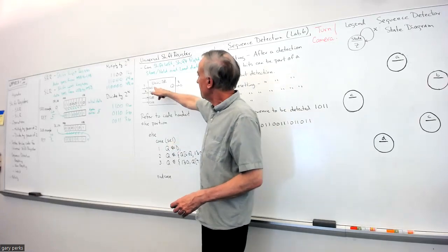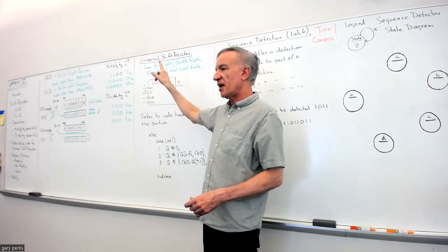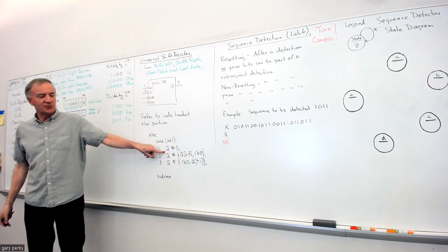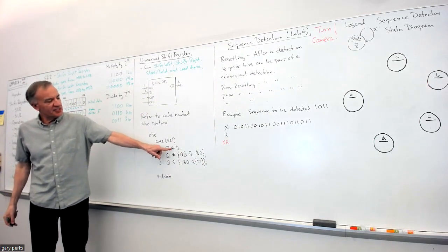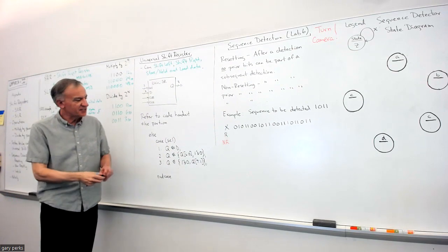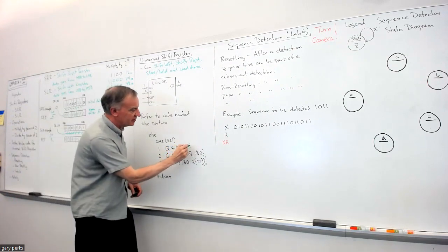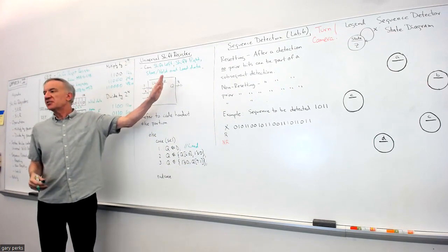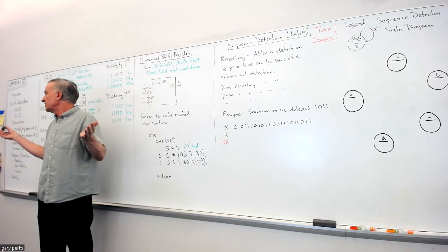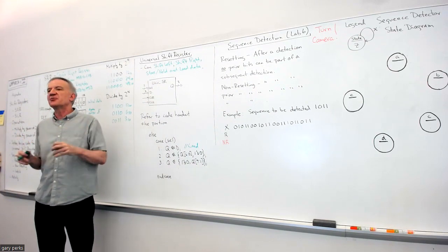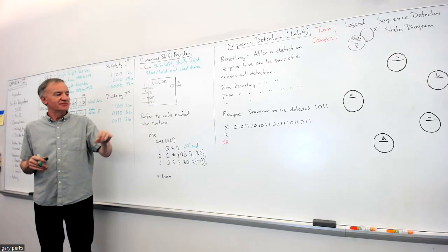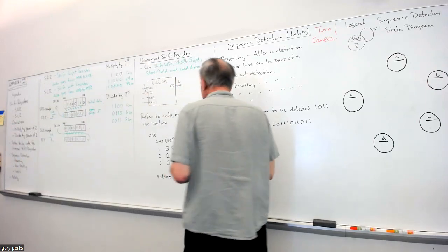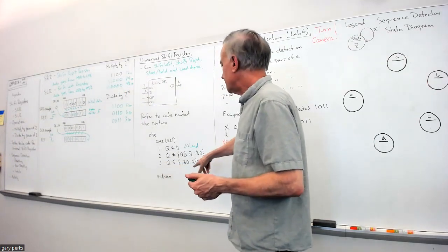So look, if our select input is a 1, if I put a binary 01, well, it's going to be this option right here, where Q is going to be assigned whatever's on the D input. So you see, this is when it's loading. This is when data on the D input would be loaded to the Q output, just like in a memory register when we do enter. Enter and load, same thing.